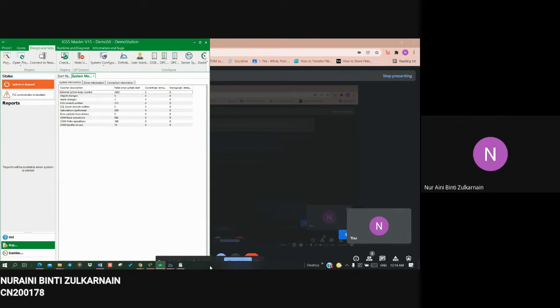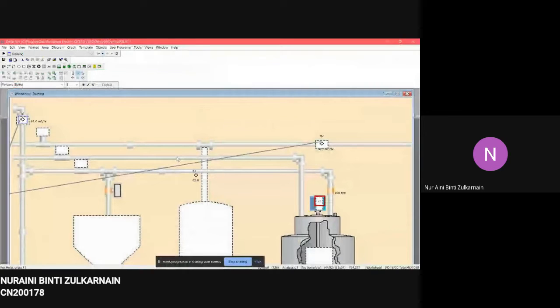Based on all the 5 tasks that were given, let me explain the purpose of this exercise. The purpose is to create new objects for the process diagram and to use the copy and paste function to replicate objects of identical nature. For this task, we need to create two flow gauges, analog objects Q1 and Q2, as well as a counter for the operational hours of the mixer motor C1, and place them in the process diagram.